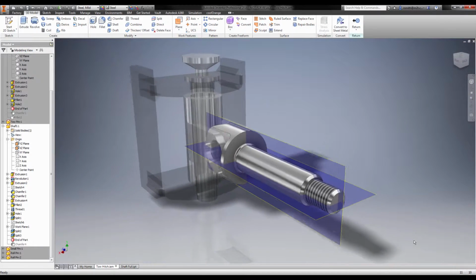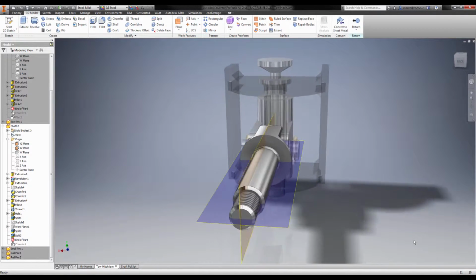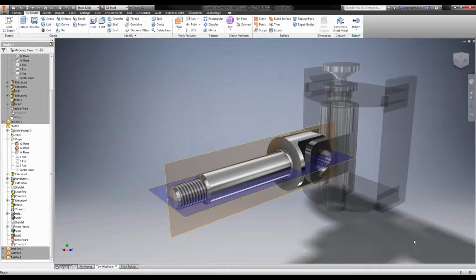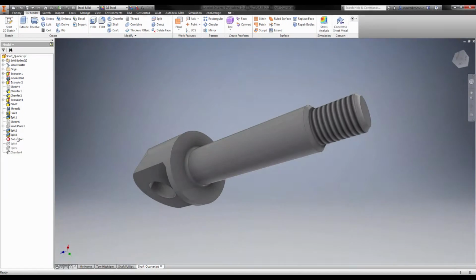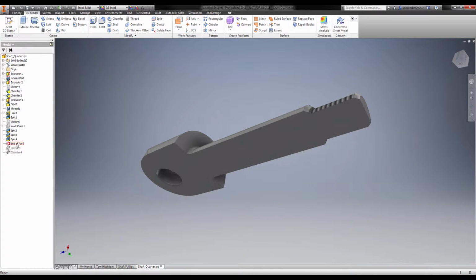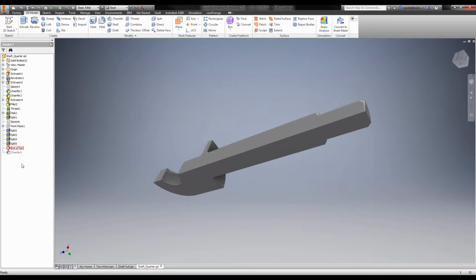If the geometry is symmetric across one or more planes of symmetry, or is close enough to symmetric that a safe assumption can be made, you can trim the model at the plane of symmetry, removing half, 3/4, or even 7/8 of the geometry from the model.